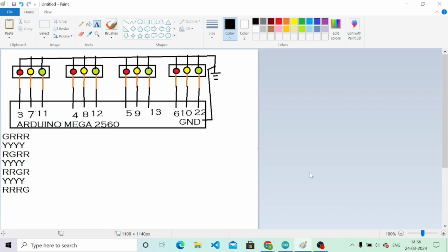This is the circuit diagram of the circuit. So now, what is a traffic light control? This is the basic circuit that I will be using. Here, this is the order in which it should turn on. That is, first the green LED of this one should turn on, and when this green is turning on, all three red LEDs should be turned off.